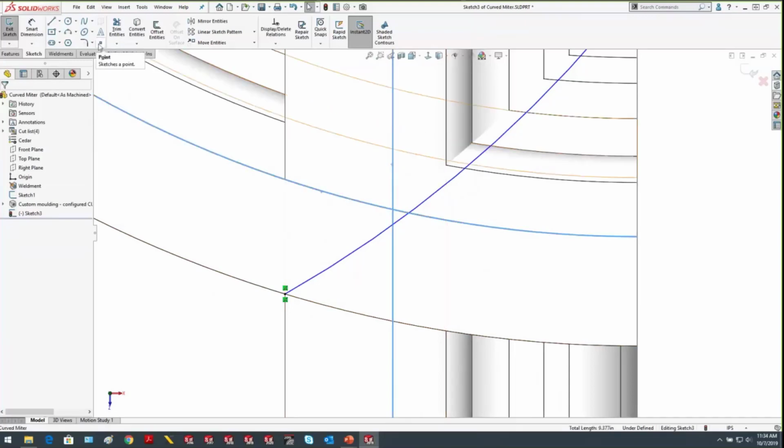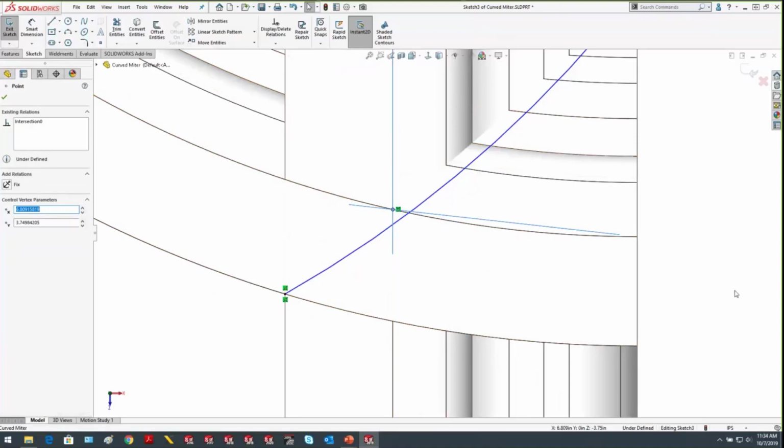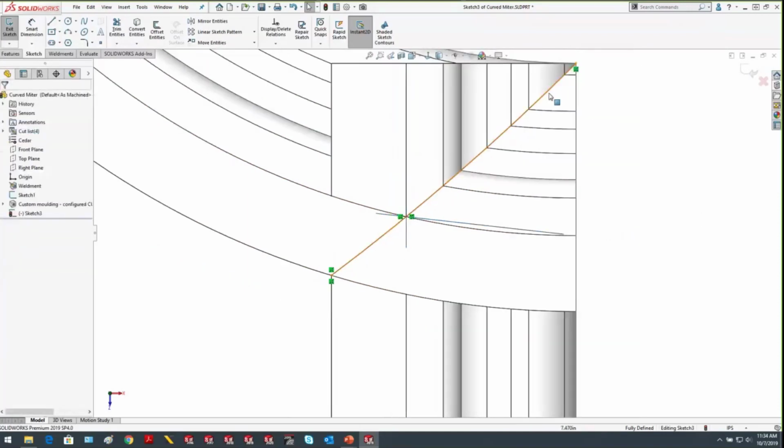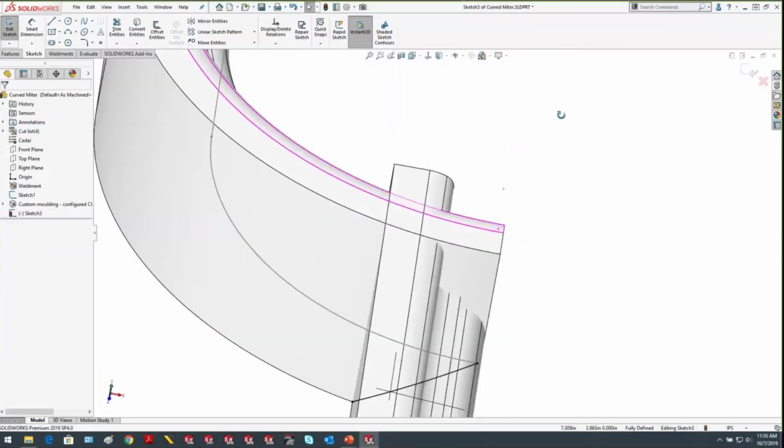And if I use the sketch point command, it is then going to create a virtual sharp at the intersection of those two edges, which I can then use to make coincident to my arc to lock my arc in on the correct curvature. So that was virtual sharp. It is a sketch command. If you have two entities selected that intersect each other, so two lines, two edges, it will create a virtual sharp, a point that you can snap to. So my arc is then snapped to that point.